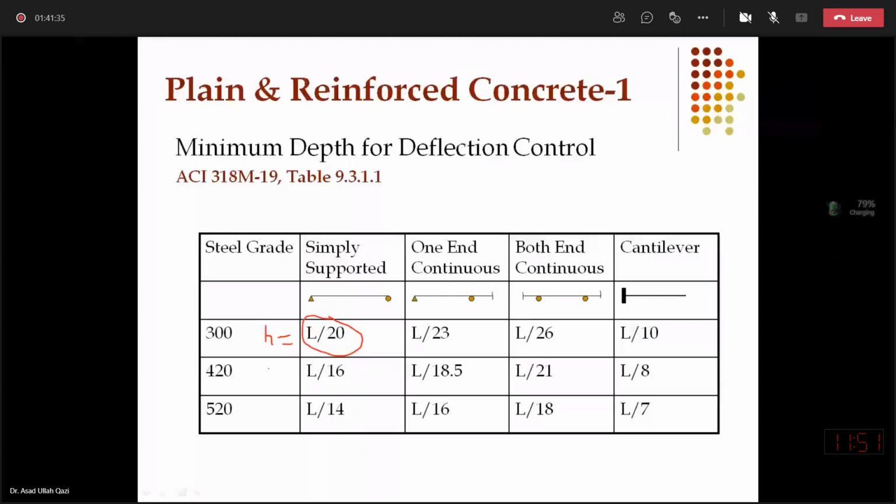So in flexural members, if you will use high strength steel bars, in order to develop equilibrium and to control the deflections, because of higher grade steel, you will have higher yield strain limits, more rotation will be allowed. So you need more h, and as a matter of fact, more C value, compressive force, to develop equilibrium with tensile force.